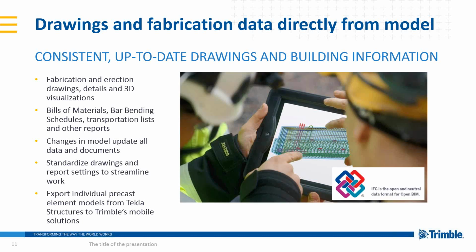In addition to just drawing information, it's possible to create separate models of individual cast units from the model by using file formats like IFC. Model files can be utilized with Trimble's mobile tools like Tekla Field 3D, which is a mobile solution, easy to learn and does not need any special computer skills to use. So Tekla Field 3D is quite easy to take into use and can be used on devices like tablets and mobile phones. And especially with complex elements, easy to read 3D information helps to understand how the elements should be built, which might be difficult just by using drawings.